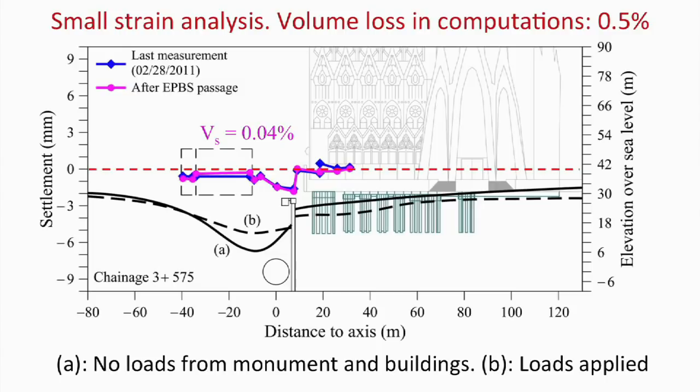Well, first, what was measured, really? This is the wall here. This is the protected area. This is 0, so no displacements in the protected part of the building. A little bit of displacements in the street itself. How much? Well, look at the scale here. This is 1 millimeter, 2 millimeters, 2 millimeters. If you compute this area here, it is 0.04%, a small amount.